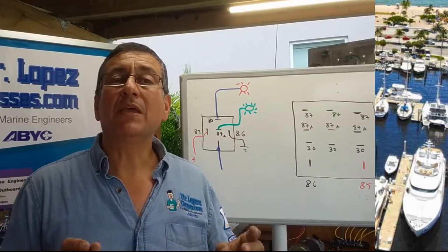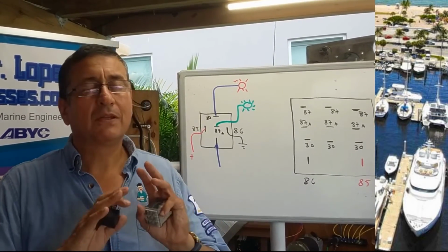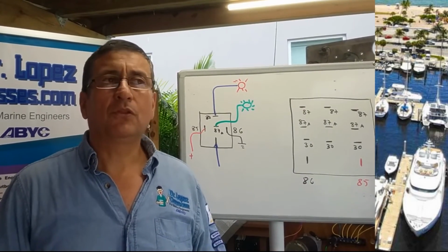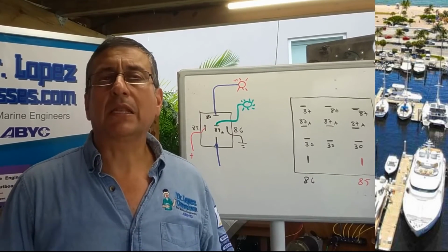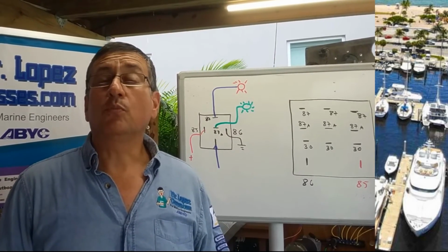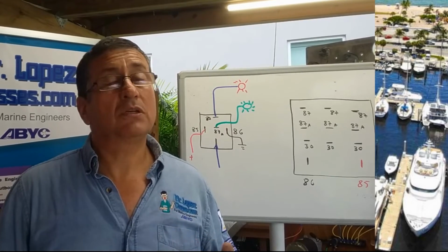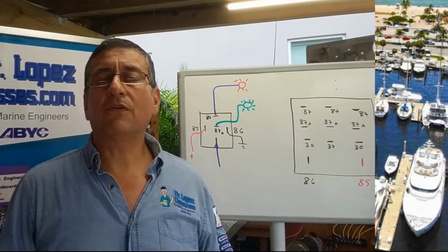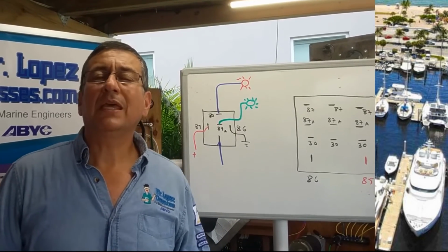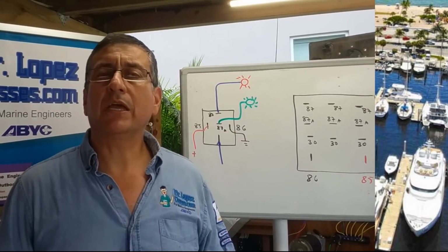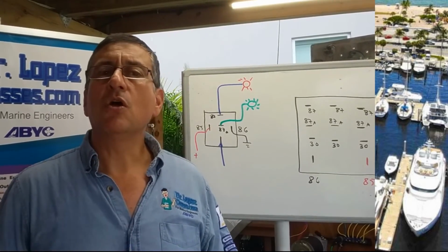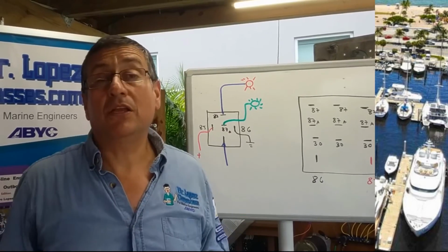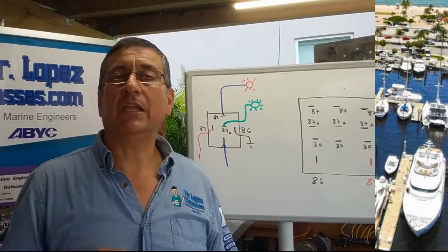Those are time delay relays. You have in your boat a lot of time delay relays to program air conditioning equipment, hydraulic systems, to start the generators, start the water makers. A lot of time delay relays we are going to use. In our class of auxiliary systems, I am going to explain in each equipment where the time delay relay is located and what the diagnosis is. The diagnosis is exactly the same as the bus relay.